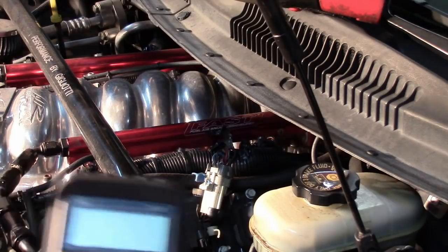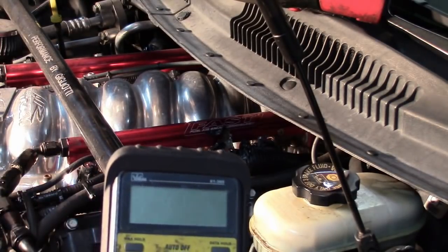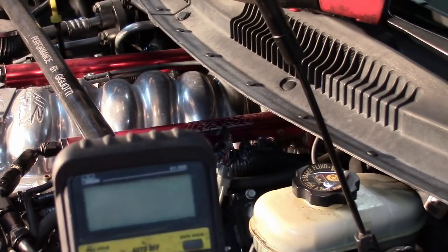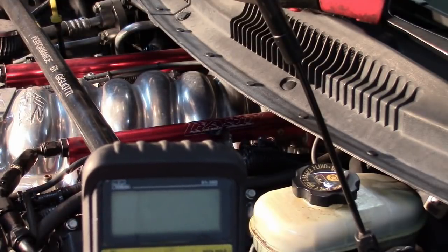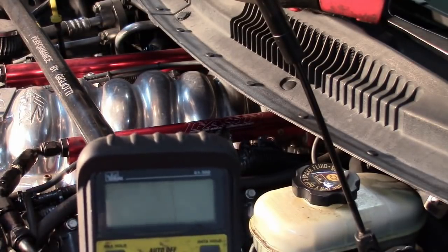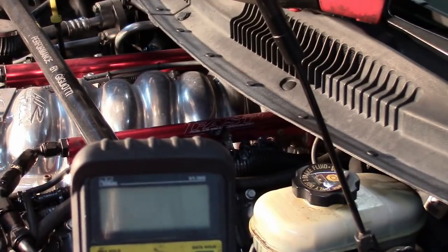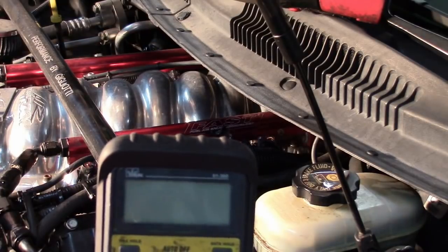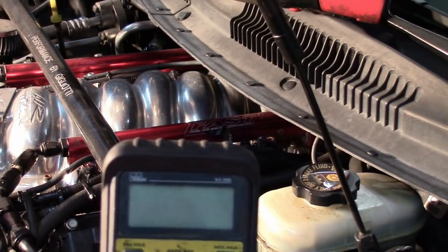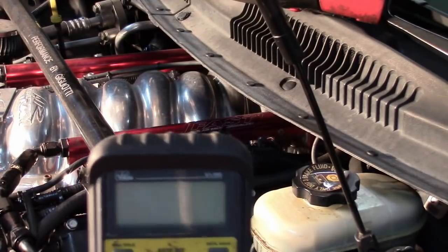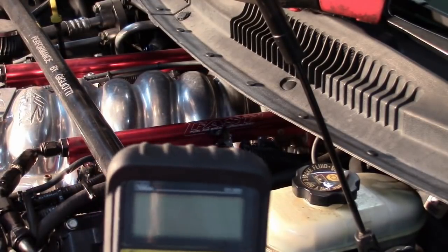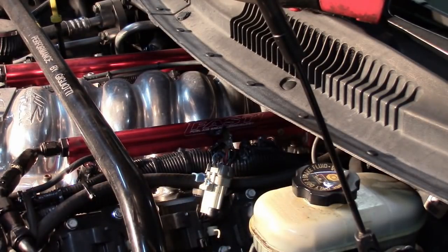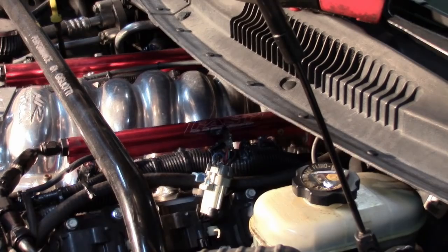As you know, generally my favorite way is the DVOM. I just like the quantitative output. There are going to be limitations actually on this. Really, especially for some of the input signals, the scope is the best way because you want to see that square wave. The other thing is that because this is going to be very fast and rapid, my DVOM is going to jump all over the place on the input signals. A test light actually would be a better way to do it if you didn't have a scope, but really the scope would be the way.